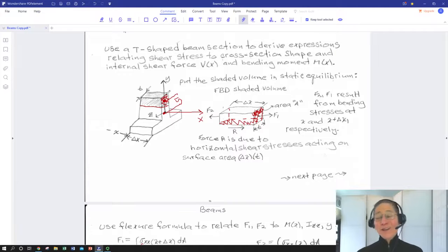And furthermore, we know that tau xy has to equal tau yx at that corner due to the symmetry of the stress tensor for shear components, anything not on the matrix diagonal. So we know that we're going to get a minimum out there because it's 0 on the opposite face.